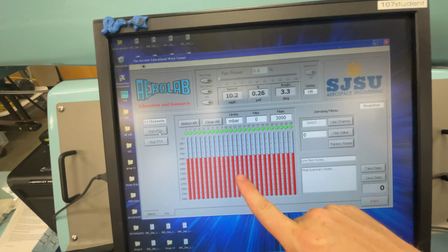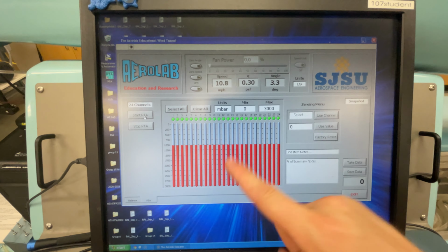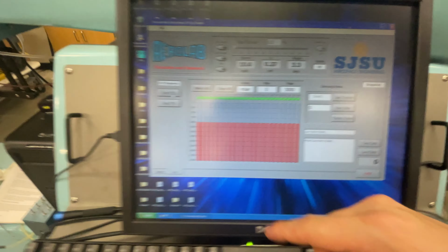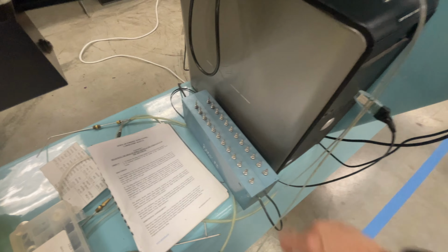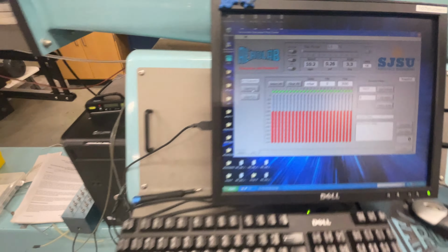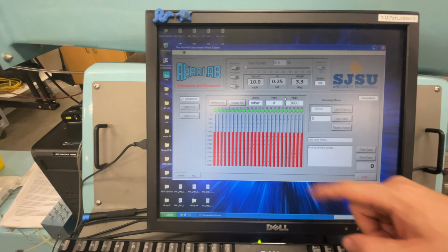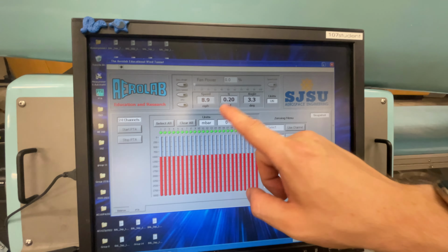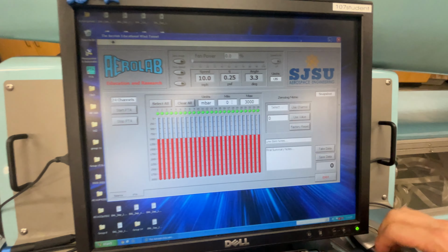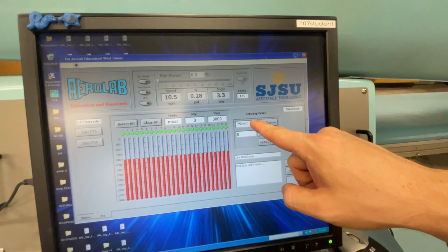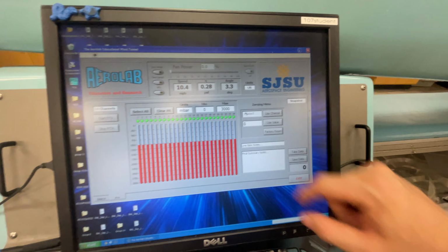This is not the version of the software we're using for measuring forces. This is used for measuring pressures, and a lot of them. And those will all be measured via tubes connected to this box down here once we get to that part. The only thing to note about this that's kind of unique is that this doesn't auto range the axes. We have to manually set a min and max. And also if we want to calibrate the sensors, we have a zeroing menu. Instead of a tare balance button, we have a button where we can set the value.